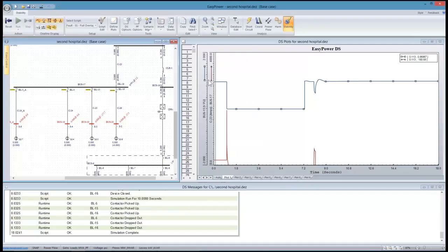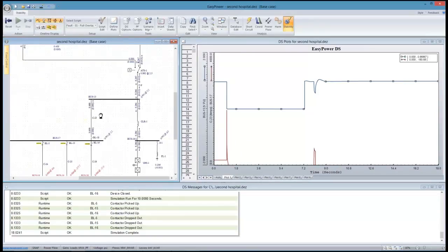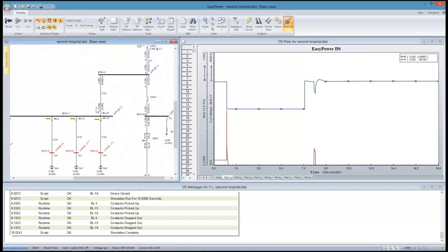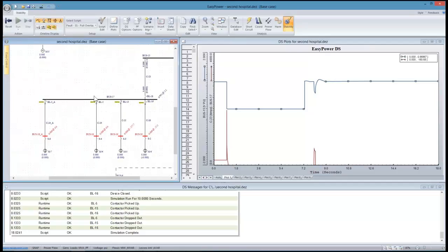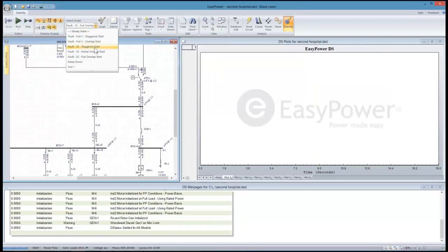And here on plot 1, we're looking at the voltage on bus 15, which is where the tie-in is for the elevator controls, and the current on bus 17. That's the total current that's being drawn, and you can see that as we try to start the motors, everything started and then hiccuped. So let's reset this, try a partial overlap and see if they survive.